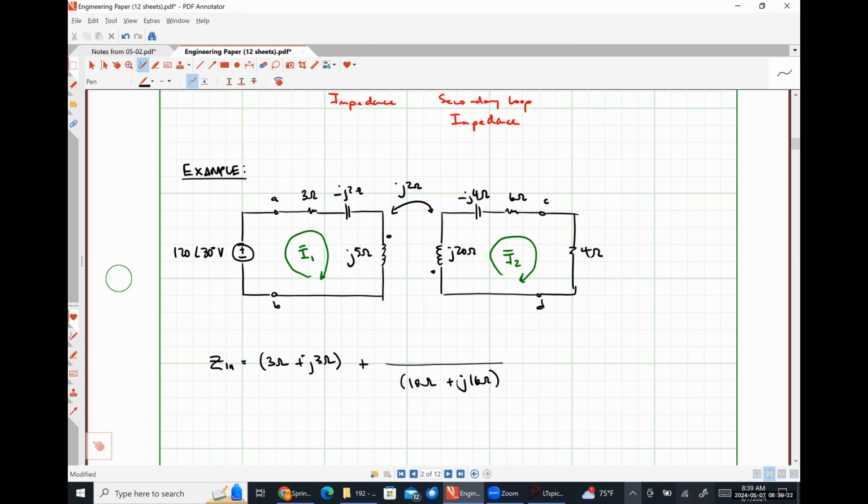So in the numerator here, we effectively just need the magnitude of the impedance of our mutual inductance, right? So we don't worry about the j, it's just whatever omega M was, and then we square that. So what would be the omega M part of our mutual inductance? So not the j, just the 2 ohms.